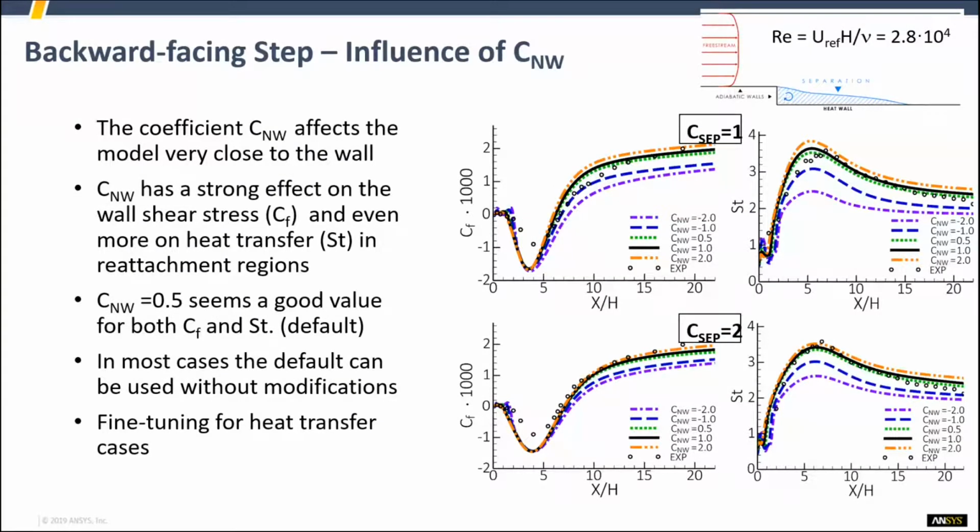So in this case, we've got our near wall, and we're looking at the changes in behavior of a backward facing step, the changes in the separation, so where it separates. So we've got our coefficient of friction on this wall here. Our coefficient of friction is going to be positive with the flow direction when it's reattached.